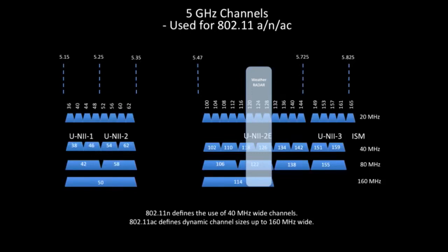With 11AC, there is the inclusion of channels 144 to just add another pair to that middle band. So channel 144 was added, but isn't necessarily supported by the 802.11n devices and lower. So if you're turning on a 20 megahertz 144 wide channel, some devices might not see that. As well, up at the end, channel 165. It's a little bit of a special frequency.